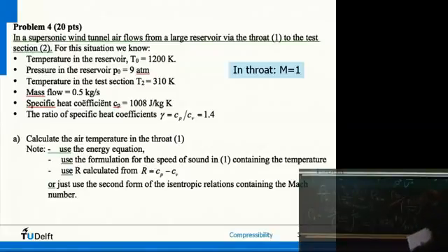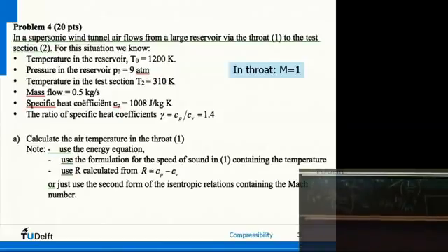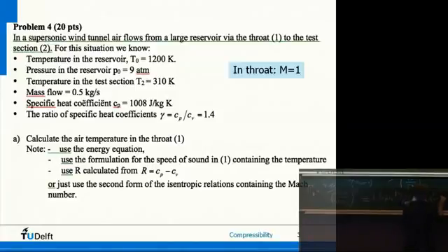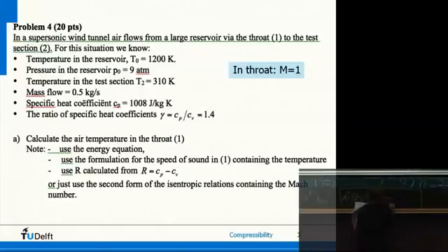Oops, are we done now? Almost, because the question was the area in the throat. Mass flow we had, speed we had in the throat. Now we know the density in the throat, so now we can find the area through a very simple relation. So A star is equal to m dot over rho star V star, so that was a half. Rho I just computed, 1.674. And V we had from earlier, 640.